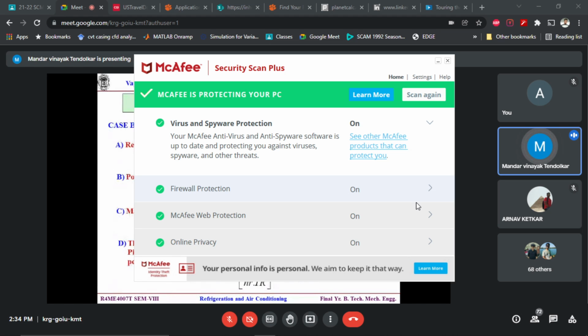Not reduced, it will increase, correct. Mass flow rate will be increased because your refrigeration effect is reduced. And the displacement also is increased, and power consumption also. And if the power consumption is increased, COP has to reduce. So our earlier case was a COP of 4.056. Now it is 0.6 directly.